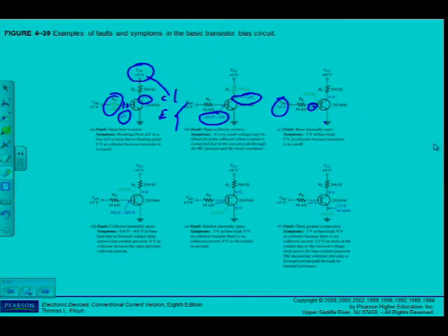Also 3 volts. So I can see that the base must be internally open, because I'm measuring up to the base and I get 3 volts. It should have been approximately 0.7, so it means again that the transistor is in cutoff. Of course, I'm measuring over this collector emitter of mine. I'm measuring a voltage which is VCC. Means the transistor is in cutoff.